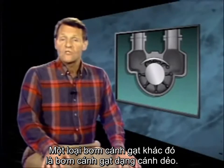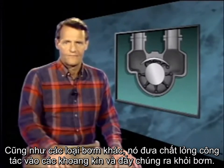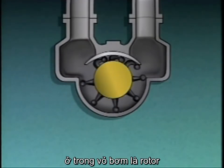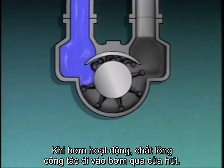Another type of vane pump is called a flexible vane pump. Like other types of rotary pumps, flexible vane pumps trap process liquid in spaces and move it through the pump. In this illustration of a flexible vane pump, we can see all of the basic parts. Inside the casing is the rotor, and attached to the rotor are the flexible vanes. As with the sliding vane pump, the rotor in the flexible vane pump is offset from the center of the cavity that it's in.